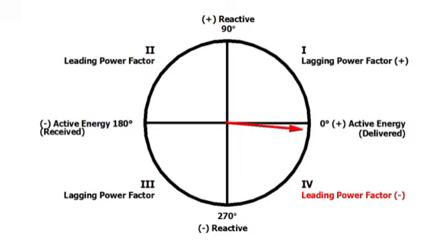In the case of the capacitive load, the load supplies reactive power. Thus, the reactive component is negative as here the power is provided by it. But for inductive load, the load consumes reactive power, hence the reactive component will be positive. The value of leading power factor, for example with capacitive load, ranges between -1 to 0. While for the lagging power factor, for example with an inductive load, it lies between 0 and 1.